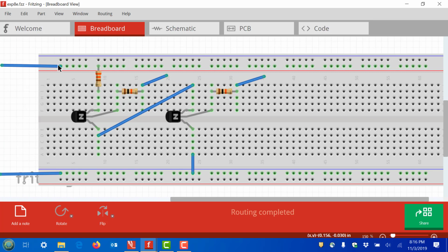So what we're seeing is here's a 5 volt rail. The 5 volt rail is right here, and here's a 330 ohm that we're sharing. So here's the first transistor, here's the collector, the base, and here's the input for it. But the emitter of 1 is going to be the collector of 2. So this is the collector of the second transistor, and it's tied to the emitter of the first transistor, as you can see by the highlighting here. And the base, of course, of the second transistor is over here. And again, this one you can put up to 5 volts, down to ground. Similarly, you can put the transistor 1 input up to 5 volts or ground, and that's what you'll be doing. And of course, the emitter of the transistor 2 is tied to ground. And that's what you're seeing over here.